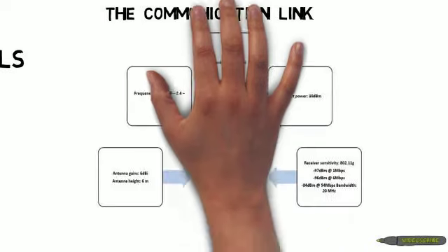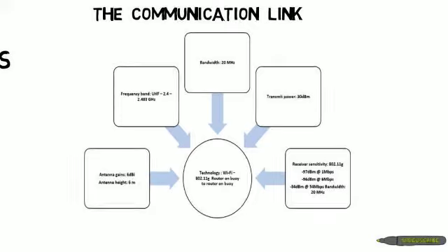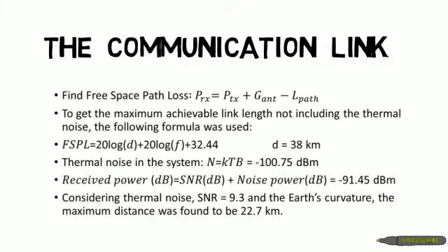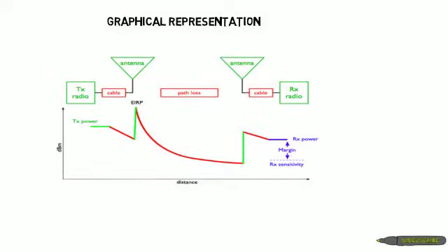The communication link was designed using Wi-Fi 802.11g and the following parameters. The maximum link length was determined using the practical limits: antenna height, receiver sensitivity, transmitter power and antenna gain, and the fundamental limit: free space path loss, all the while keeping the desired quantity and quality metrics for this application in mind.